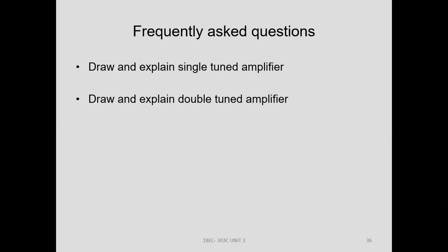Generally, that is called loose coupling. With loose coupling, the EMF induced in the secondary coil is less, and it offers small resistance. That means Q is high. The gain will be maximum at the resonant frequency, and it decreases below and above the resonant frequencies.